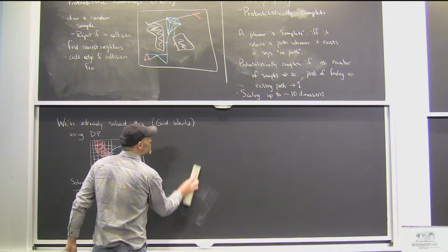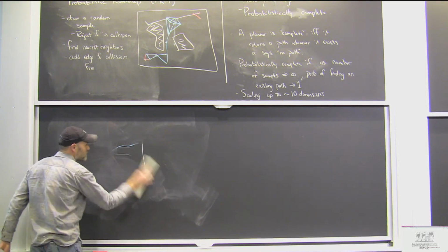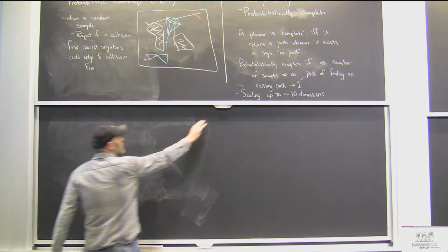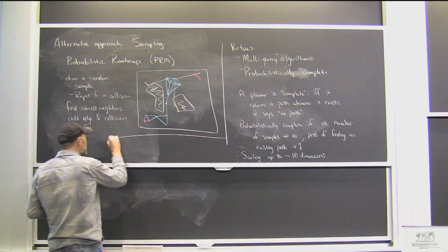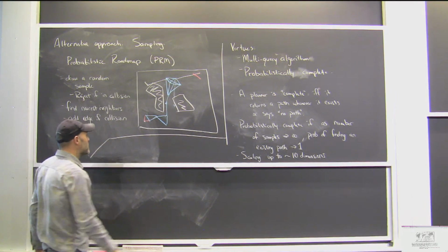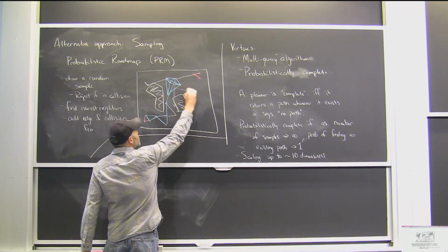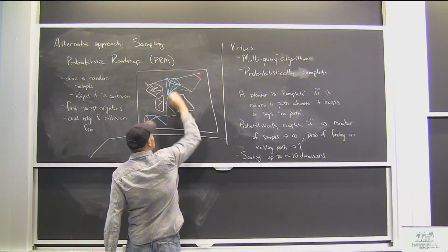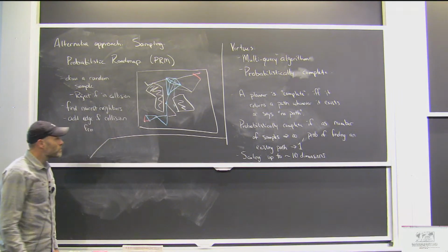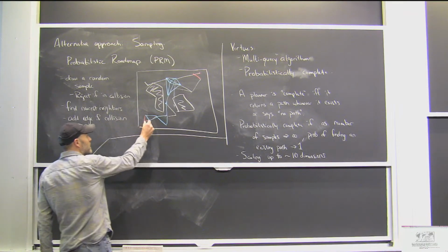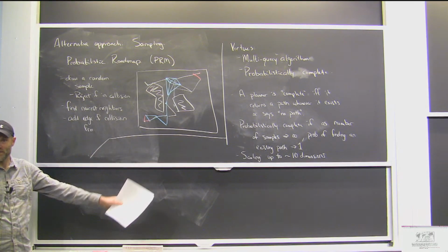There's one other virtue I'd like to point out, which probably most people wouldn't bother with, but for me it's a big deal, especially since we've talked about trajectory optimization a bunch. One of the things I really like about these algorithms is that if I've made a graph, and then I have a new start and a goal, I just do any of my favorite graph search algorithms to find that path. The length of the path in terms of the number of segments in my discretization is whatever it needs to be to find its way from the start to the goal.